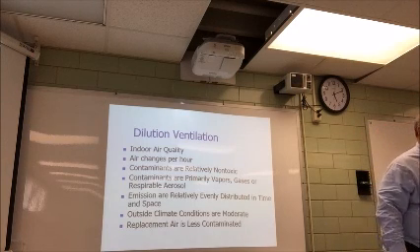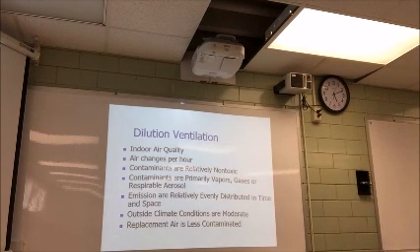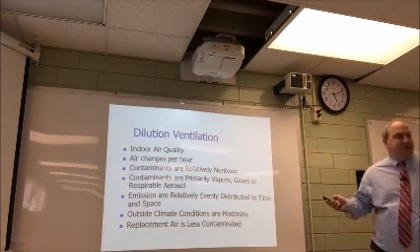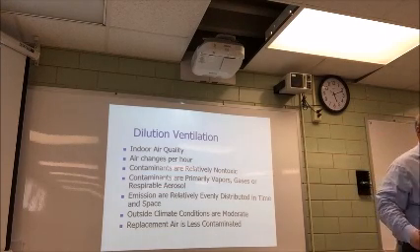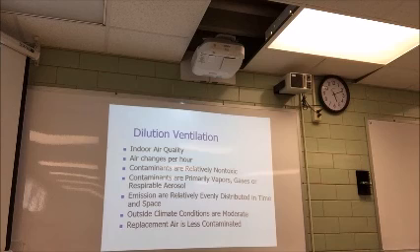So that was kind of your local exhaust ventilation. Let's talk about some dilution, and we'll go back. Dilution ventilation. I want you guys to see one thing that you'll see over and over again. Dilution's used for non-toxic. Why would we worry about whether it's toxic or non-toxic? What's dilution? If you guys are handling a chemical right here in the middle of this room, what would dilution do to that chemical or compound?